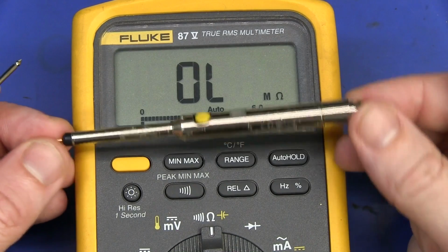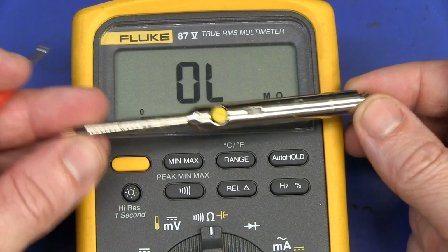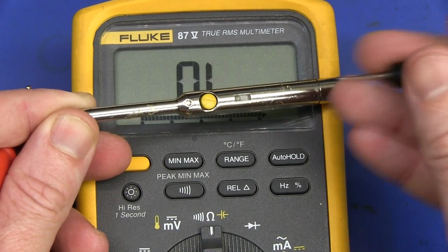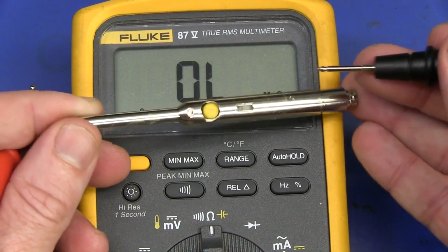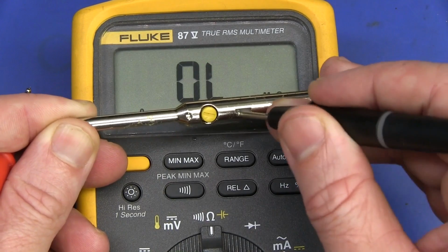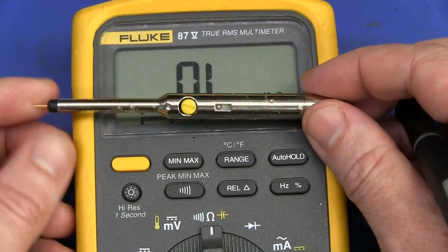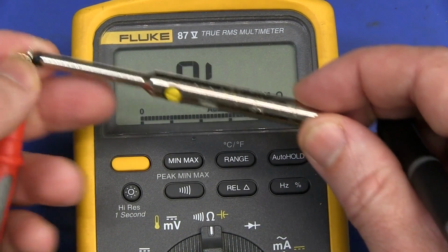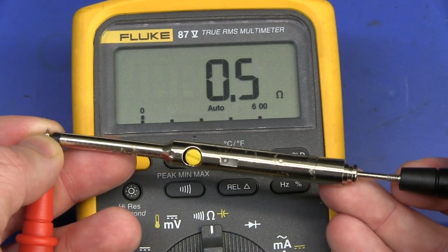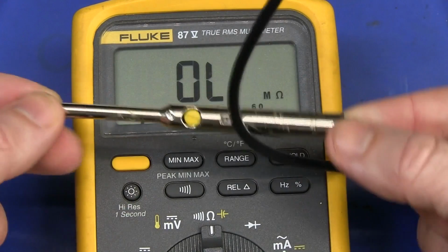Well, to show you that there's nothing, no funny business going on in this tip here, I've taken apart a times 10, switchable times 1 times 10 probe. Yes, it is different to the Rigol. It's not a Rigol brand, it's a Velleman brand. It's just a cheap old one I had lying around. And there's the times 1 times 10 switch. So times 10 is down in that position down there. So we're up in times 1 position, and that should short out the network there. So the compensation network. So let's measure between that probe point and here. What do we get? A dead short. So there's no funny business going on inside that probe, what we'll call the probe.